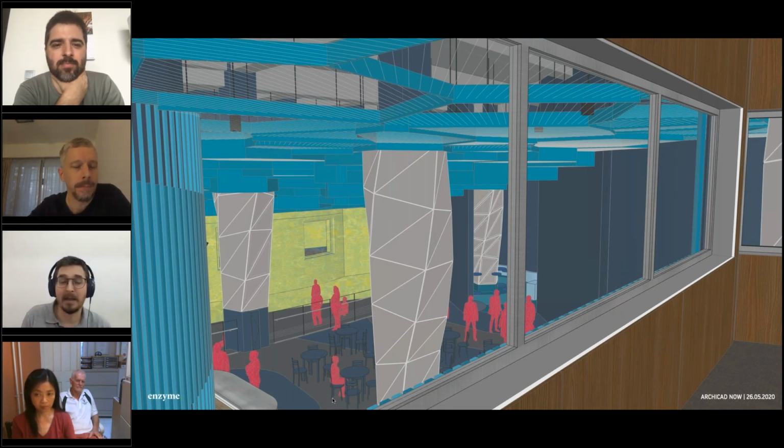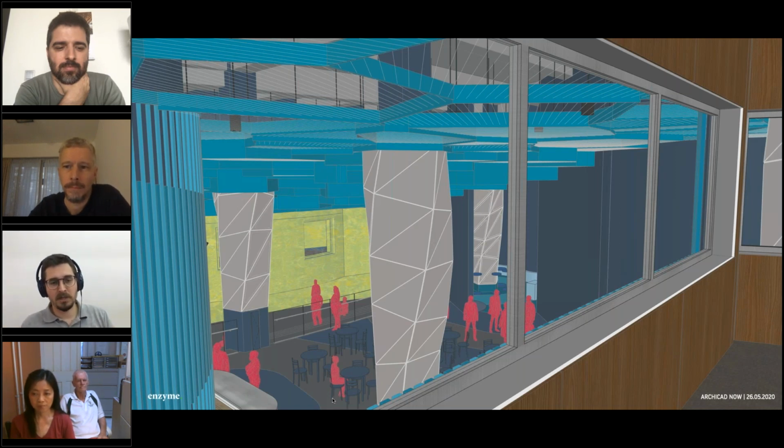plugin for Grasshopper that is called Elefront. I can send it to you through the chat. You guys can take a look. What this Elefront component does is many things, but one of them allows you to break down the scripts, the Grasshopper files, into smaller files, and then you can reference them. How can I explain this? Imagine that you do all the script of the columns, and at the end you have, for example, the outlines in plan. You can bake that into Rhino as a physical model, and then you can link that into a new Grasshopper file.